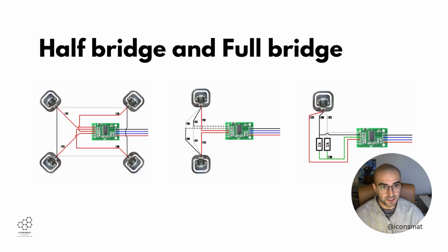You see this 1K, these are external resistors. It is not recommended to use only one strain gauge in a load cell because when the temperature changes, this can cause error in the reading. So the highest accuracy normally comes with four strain gauges in a load cell, what you see on the left side. And also the second one is also acceptable.